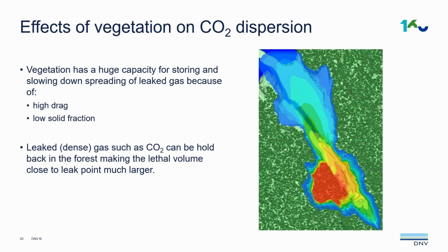In former studies in KFX, we have used thin porous wall to model drag from vegetation. This works for a small region of vegetation, but to model a forest or a large area of bushes and trees, the surface porosity approach is very grid dependent. So we are currently developing KFX so that forests can be modeled as a combination of cones and cylinders and regulate how much solid fraction they generate. So as I said, the result from this GIP will be included in the commercial release, but not before the end of the GIP, so 2025.